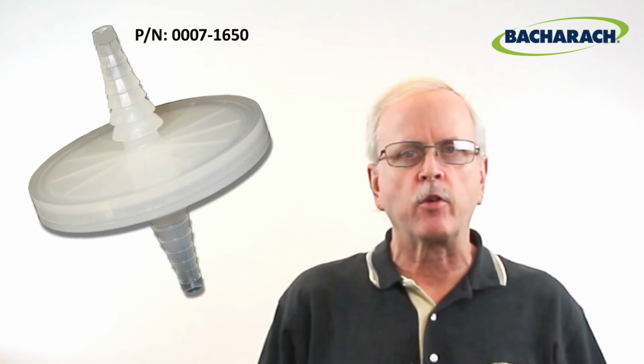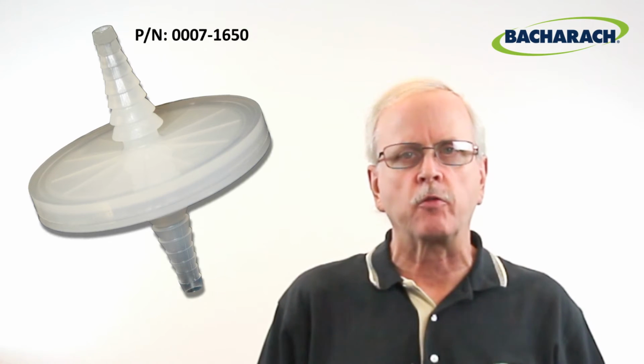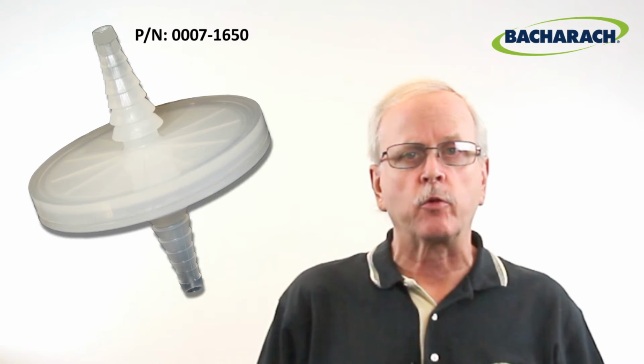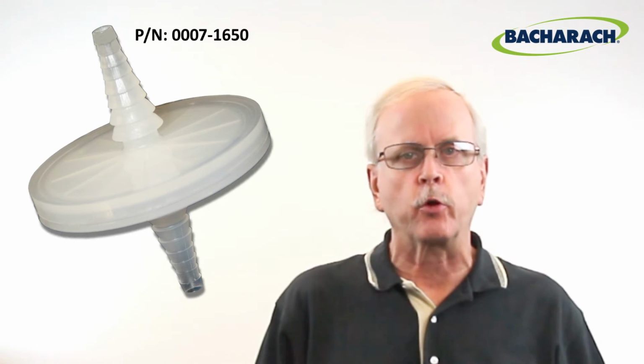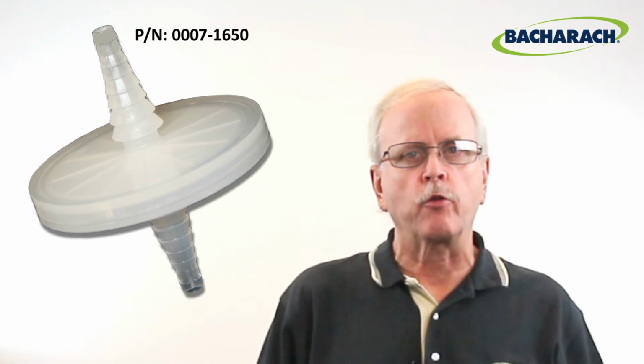If you do not have a new filter, either shut down the system or put the old filter back in. Do not operate the MZ without the filter in place. The filter prevents moisture from entering the infrared bench assembly. Replacement of a compromised infrared bench is much more expensive than a replacement of a filter. If the filter removal did not clear the no-flow faults, you need to continue your investigation.